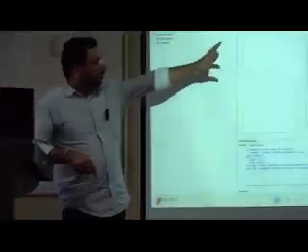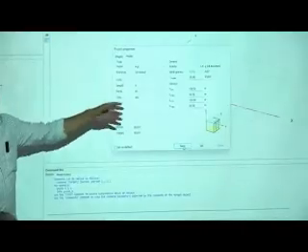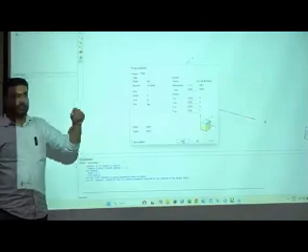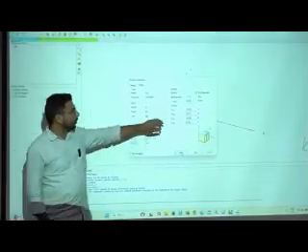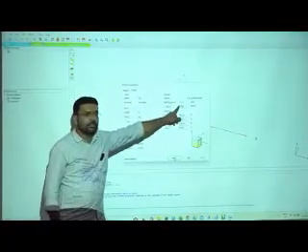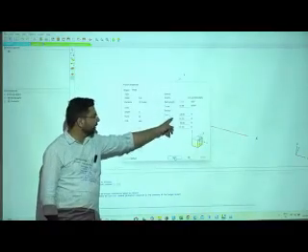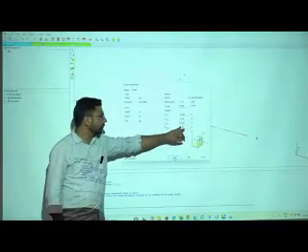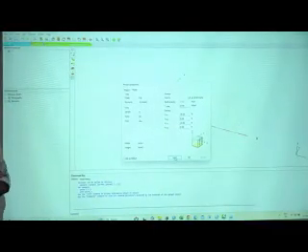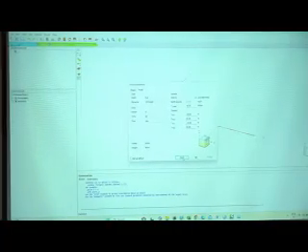In this step you give all the details here, like length, it will be meter, mm, kilometer, whatever. Force, you define the force, then time: second, minute, hour, day. Gravity is there, then water. If you change the unit here, the unit weight of the water will change accordingly. These are the coordinates, minus 15 to 15, meaning 15 meter by 15 meter is the soil domain. After this there is a next step.